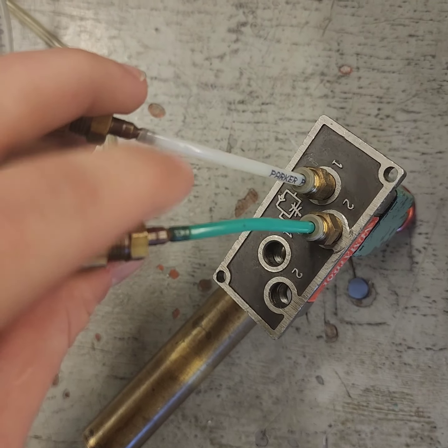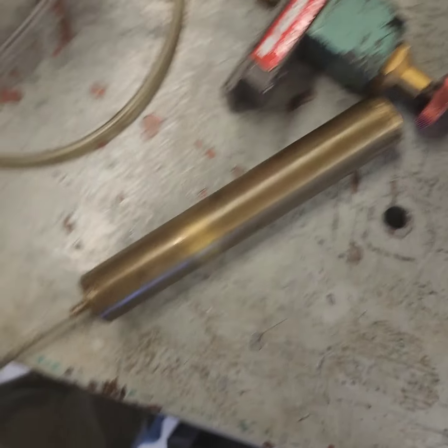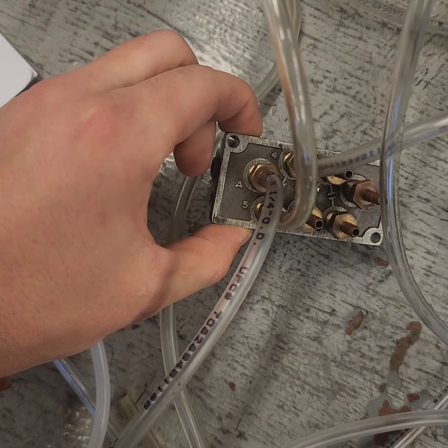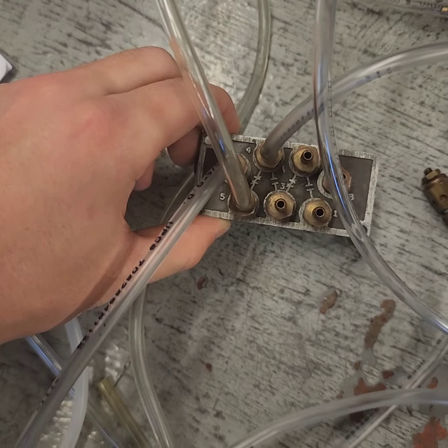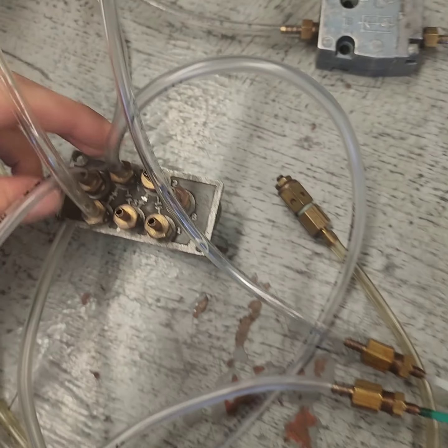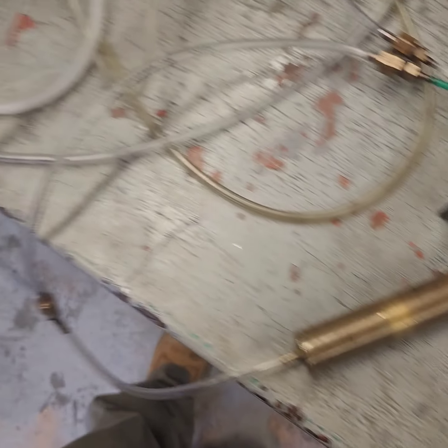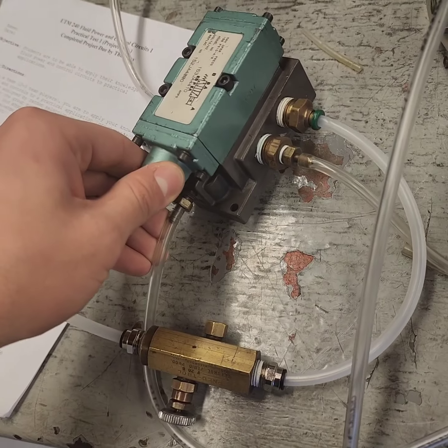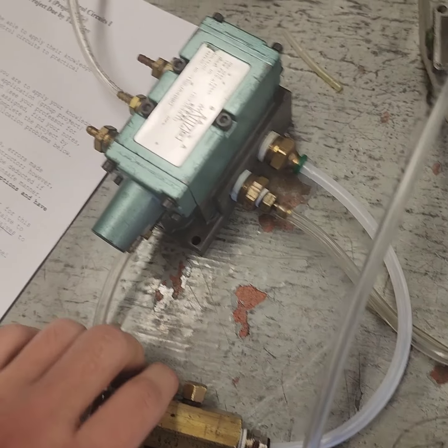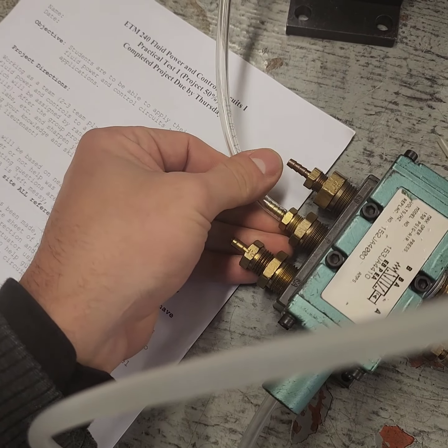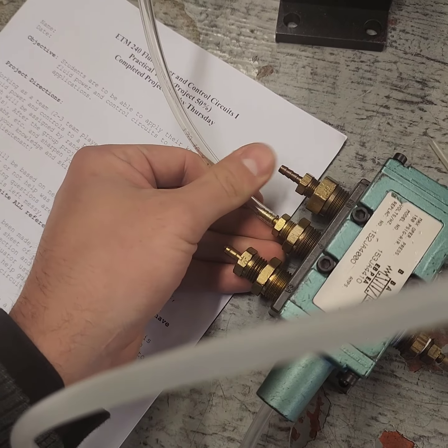So this is your pilot line coming in, this is what's going out, and the volume going to A of the control valve. You can see it's on a normally passing, going out, coming back over here, which is piloting the power valve. And then you have just your pilot line. Normally this would be larger in a real application, but for this we're just replicating it with air.